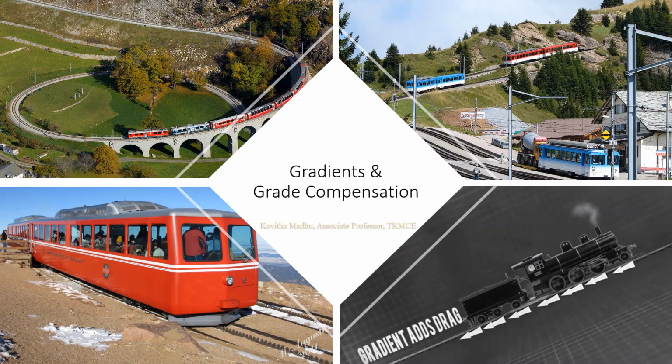Railways have a great ability to hold very heavy loads. This advantage is only significant when the tracks are fairly level. As soon as the gradient increases, it adds drag to the train, thereby the tonnage that can be held is greatly diminished. Gradient climbing is a problem faced by railway systems because it affects the load carrying capacity and also the operational speed.